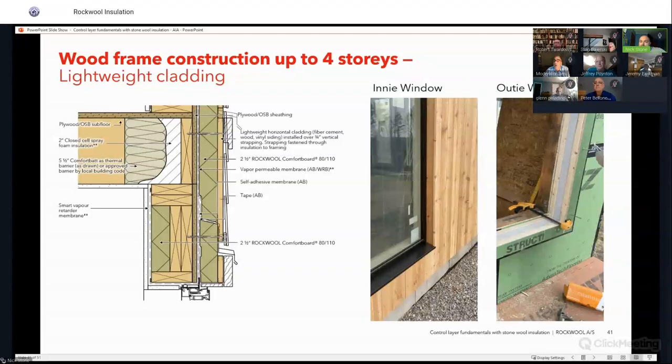All right, thanks. One last question. Cost-wise, how does Rockwool compare to other insulation, fiberglass, spray foam? So when we do a comparison with fiberglass to Rockwool, we say we're about 30% more than fiberglass, ish. I mean, obviously it depends upon the market and all that stuff, but yeah, about 30%. But we're gaining a lot more from that 30% as far as water management. Denser material. It holds its R value when things get colder much better.